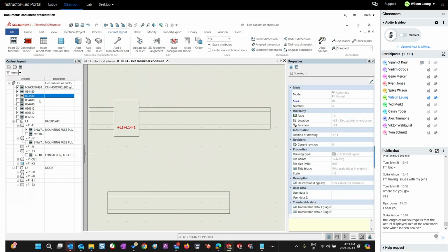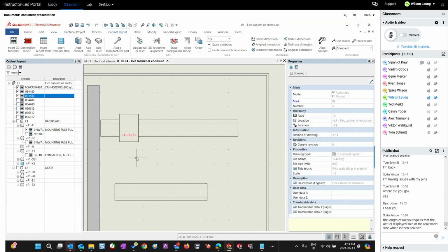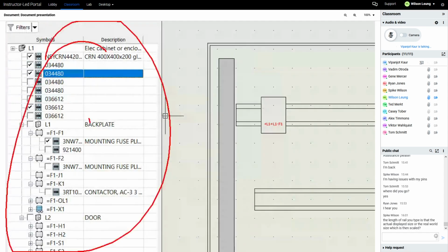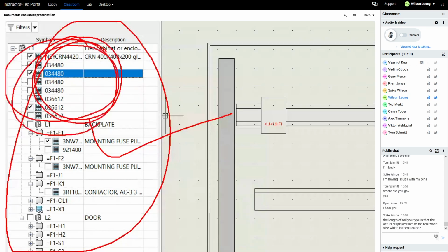Yes, Tom. The back panels. Yes. Sometimes a panel has a back panel in it. Sometimes it doesn't. I didn't see that. It obviously talks about rails and ducts, and cabinets. But does it have a back panel, or is it just assumed it's there or not there? So if you do want to show that, because anything you show in this list, do you want that back panel to show up in your bill of material list separately? Then yes. So if you add it separately here, it's going to show up in your project reports.